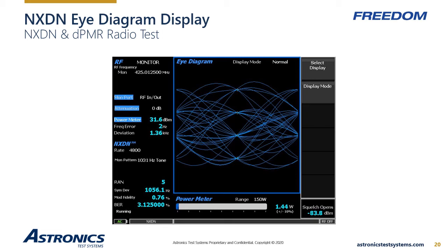Since we are connected directly to the radio, the signal is strong and we should have large open spaces, or eyes, between the symbols. If we measure a signal received over the air, the signal will be much lower. As the incoming power decreases, we will see that these trajectories start to wander from their ideal positions and these eyes will appear to close.